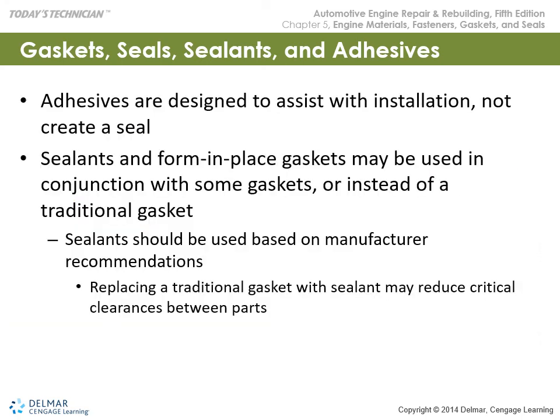Sealants and adhesives, if they're called out, are designed to be used. They form in-place gaskets and may be used in some applications, but it's based on manufacturer's recommendations. That is the key here. You never put anything in an engine that didn't come out of it, that wasn't called for by the manufacturer, period.